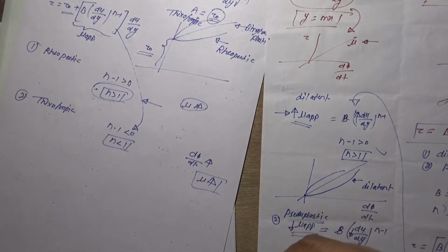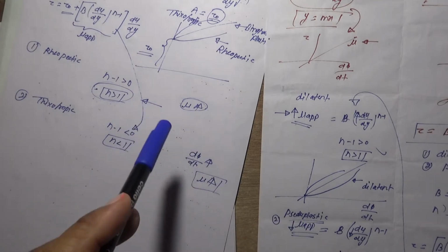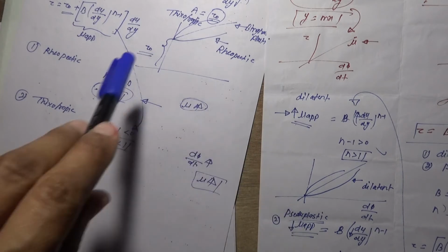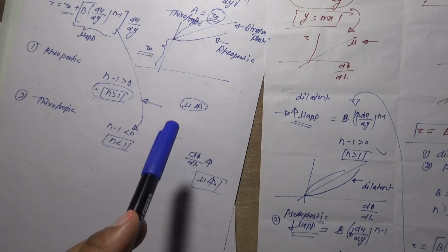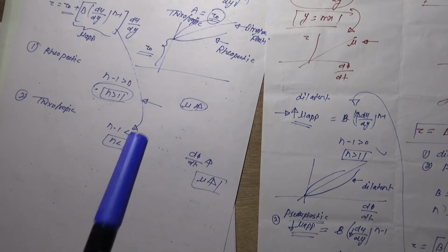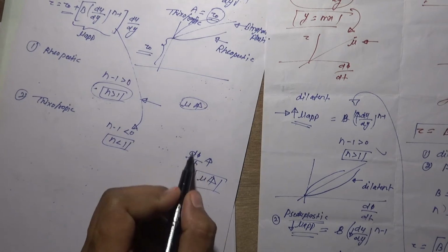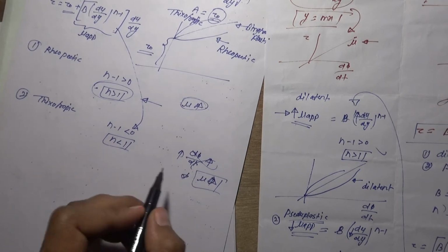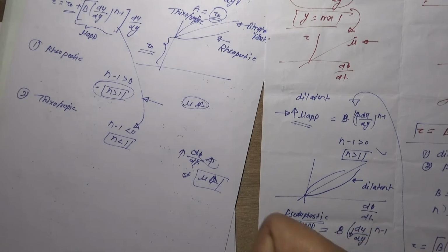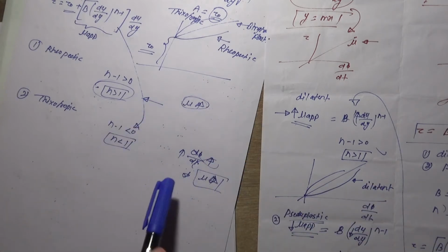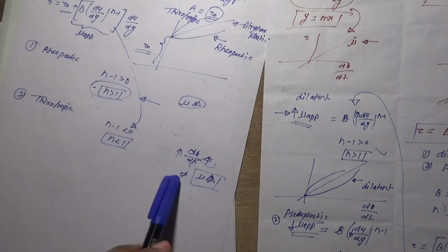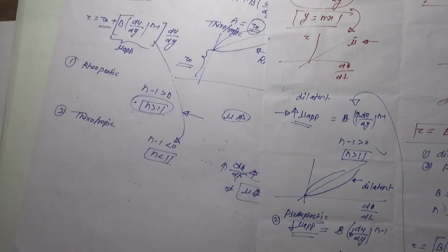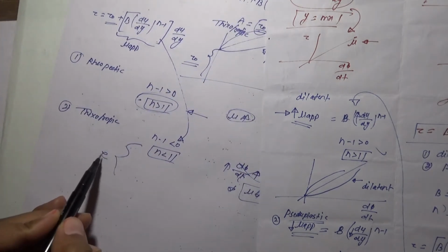Initially, if we mix the paint, the viscosity of the paint will be very high, so it rotates tightly, but after some duration of time, the viscosity of the fluid will decrease. As the rate of deformation increases, the mu will decrease, so after some time you can stir it easily, but initially you have to apply yield stress.